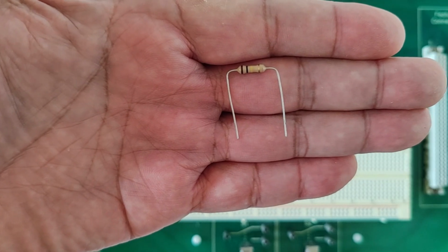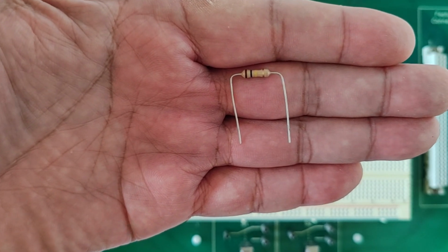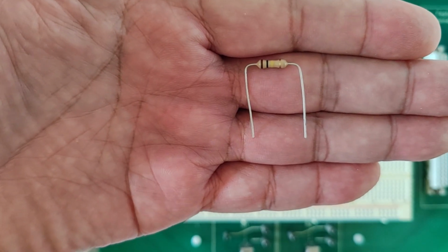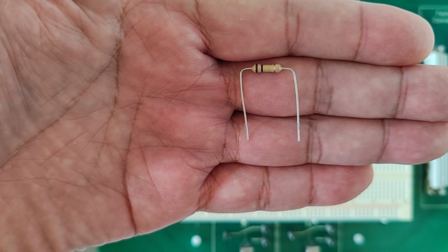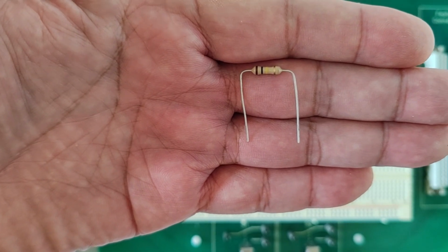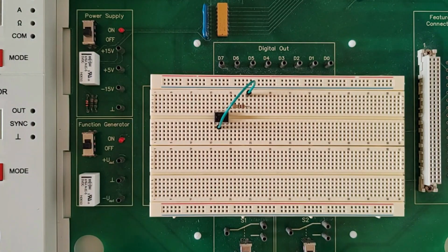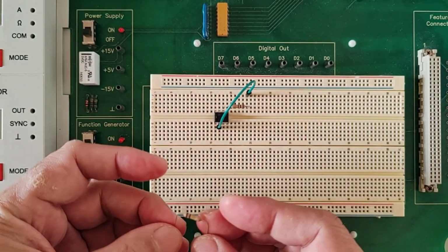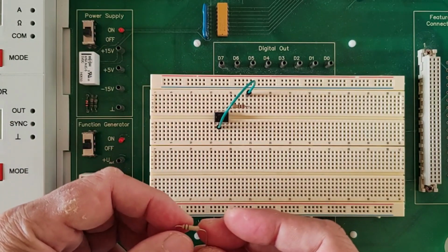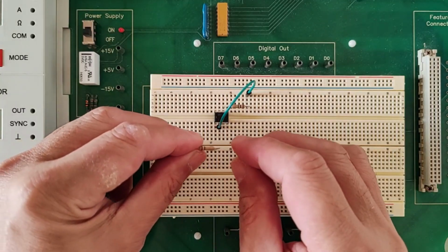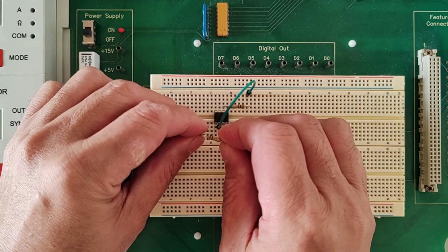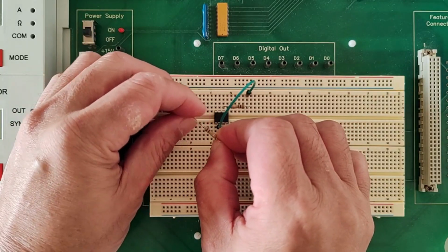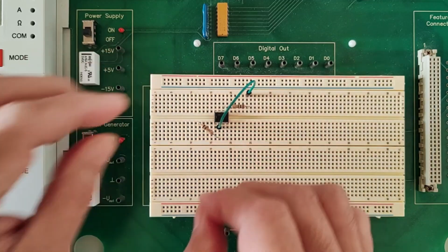Now, the input resistor is here. This is our 100 kilohm input resistor. Again, how do I know? You have to take a look at the colors on the body of the resistor. I would like to again refer you to the resistor color code video I have on the channel for reference. Now, for this resistor, I need to connect this one to the inverting input, down. Connect it here, pin number 2. I'll put the other pin maybe somewhere here at the top.